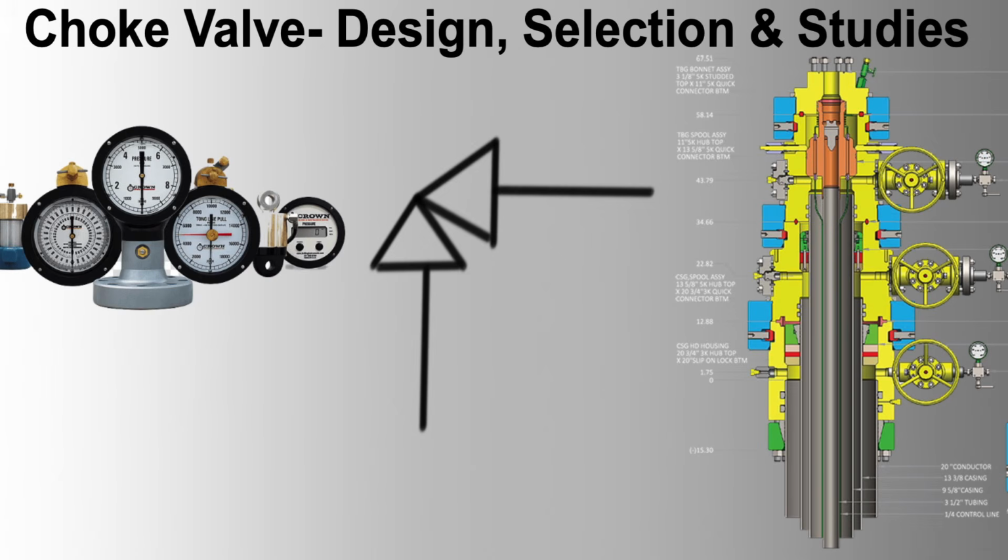Design considerations: ensure the choke valve has sufficient range and resolution to make fine adjustments. Choose materials resistant to corrosion and erosion. Operational concerns: monitor for hydrate formation and scale buildup that can affect valve performance. Implement real-time monitoring to detect and address issues promptly. Maintenance: regularly inspect and clean the valve to prevent clogging and ensure smooth operation. Schedule periodic calibration of sensors and actuators.